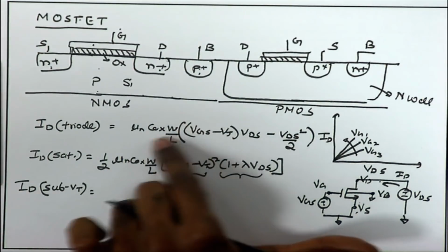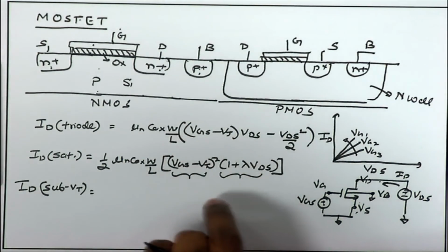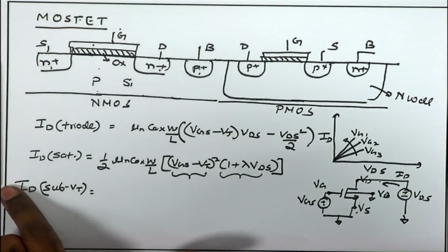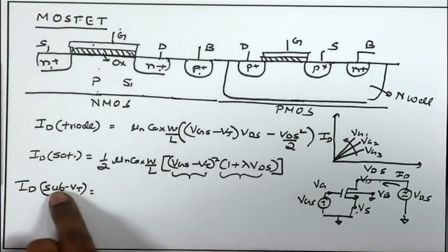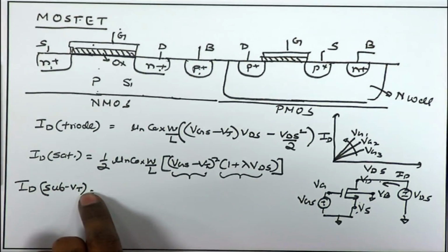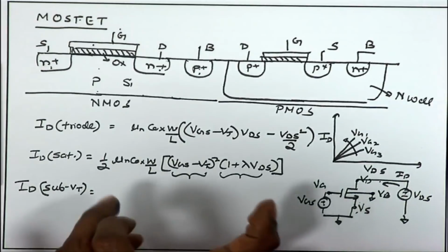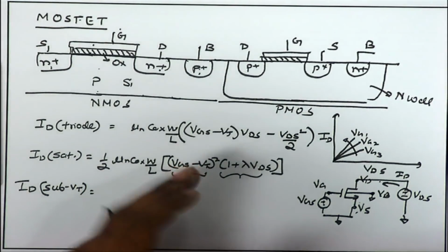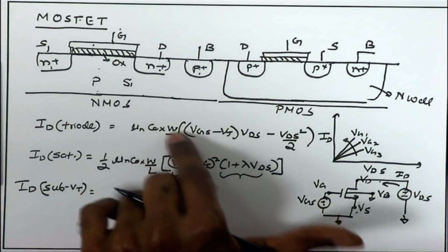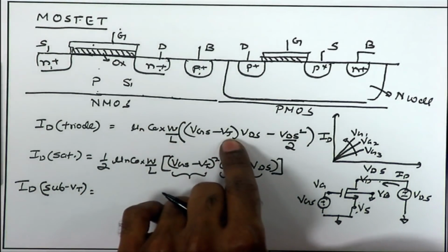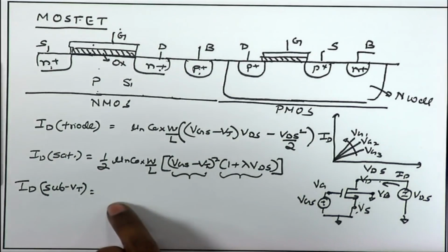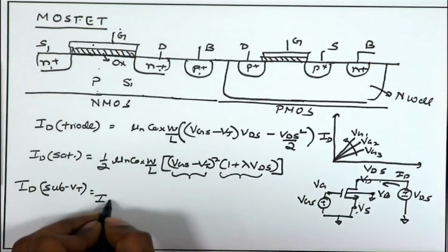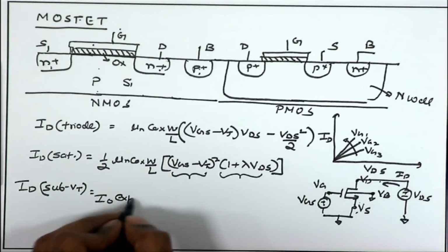We cannot apply the square law of the MOSFET directly and from there derive the small signal parameters. Rather, we need to use the sub VT equations of the MOSFET, which again can be derived rigorously through device physics, but we are going to avoid those parts. We are going to use the equations and see how the same small signal parameters that we arrive at using saturation region operation get modified when we use subthreshold operation, having exponential dependency on the terminal voltages.